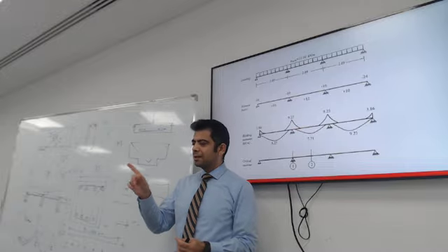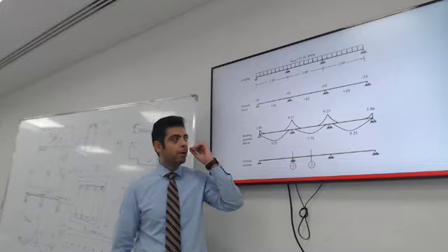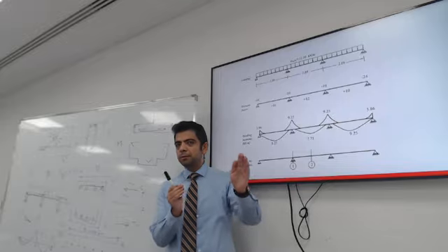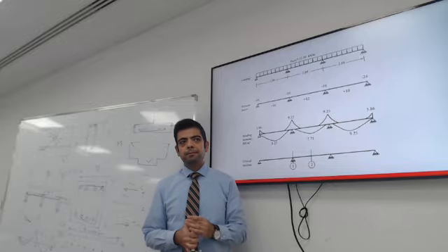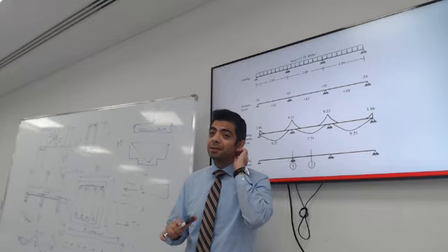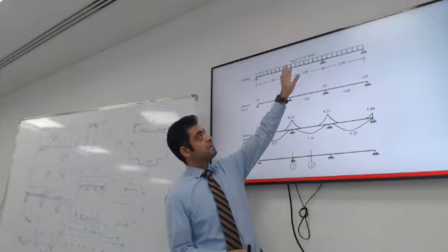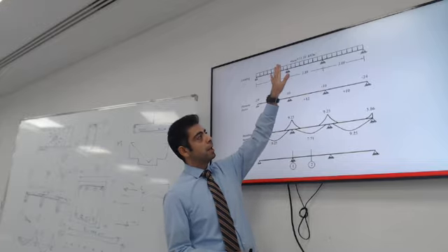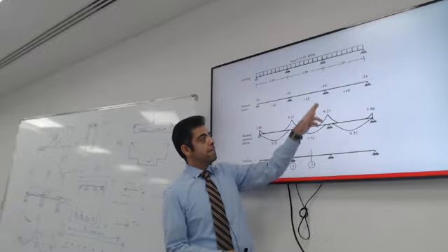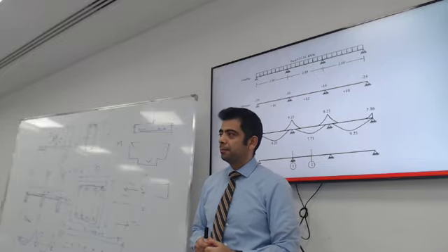No. That's an interesting thought, but it's a different diagram. The extension because of shear is a different diagram. Why the bending moment? Why are these two lines not at the same point? Why are they shifted? Yes, because of the case of loading. This diagram takes into account what if the load is maximum in midspan and no loads in opposite directions, or maximum negative with the two adjacent spans loaded.